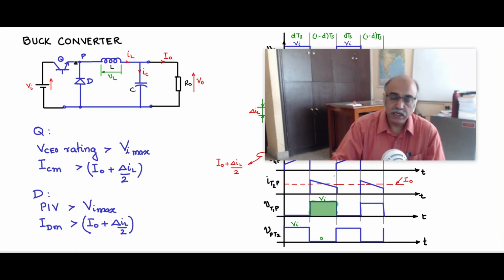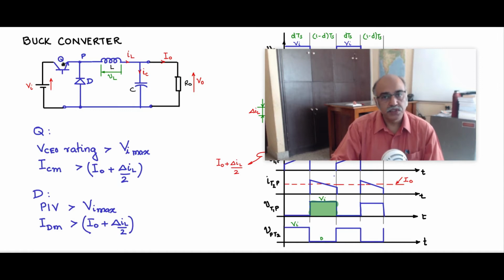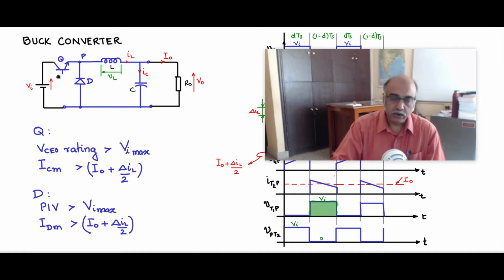Now that is what we need to study, because all these semiconductor switches have their own characteristics. For example, the BJT is a current driven switch. You need to give the proper base current to switch this on, and you have to remove a certain amount of base charge to turn this off. How do we provide for all those things in the base or the drive electronic circuits?